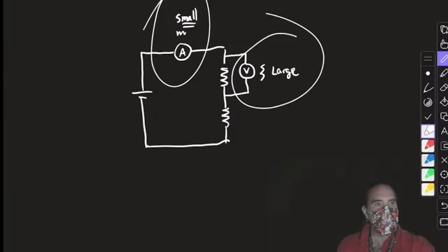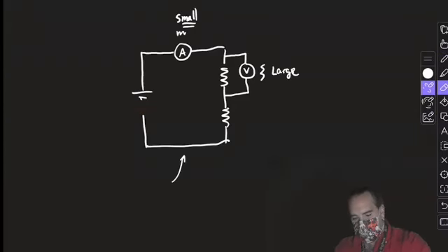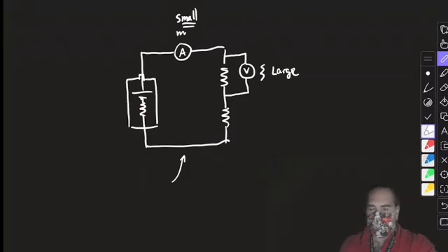This is why. Now, the other thing to think about here too is that our circuits aren't this simple. Even though that all sounds simple, the wires have resistance. There's no way around that. And worse, our voltage supplies have resistance. A real battery is a combination of a potential difference and a resistance. Now, it's not like you crack open the battery, you're going to find resistors in it. The resistance of a battery is the limit of the battery to produce current. That's what the internal resistance of a battery is, the limit of a battery to produce current.